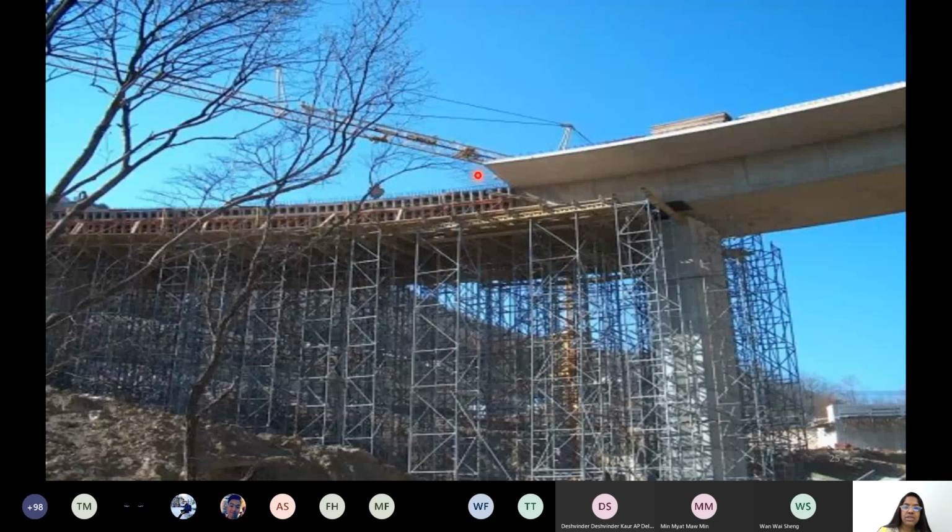This formwork should withstand this height and the sway due to the deflection due to wind for this whole exposed area, especially the end formworks, which are subject to more wind, right? So care should be taken. The end formworks are supporting this. Care should be taken to avoid deflection due to these end formworks.